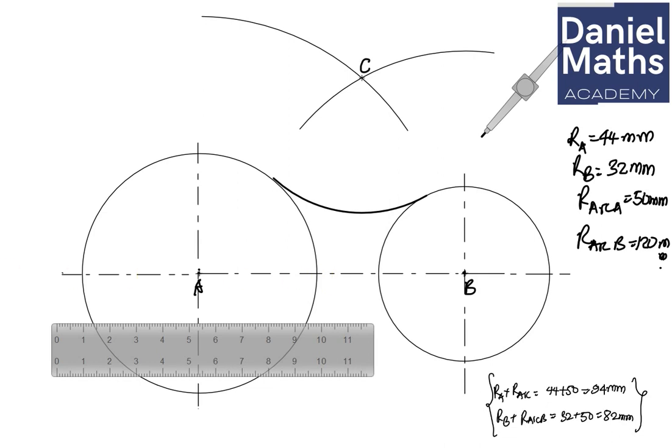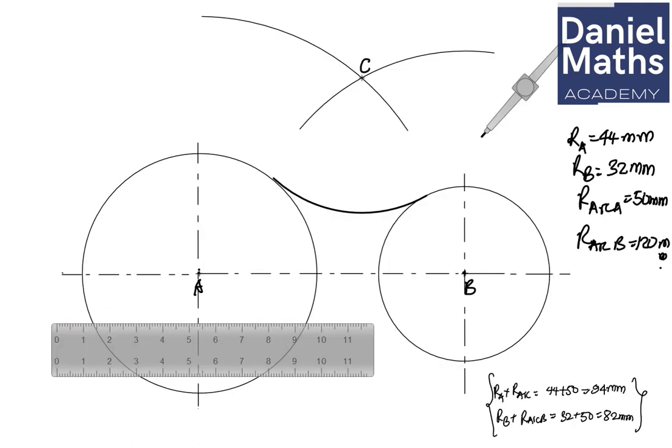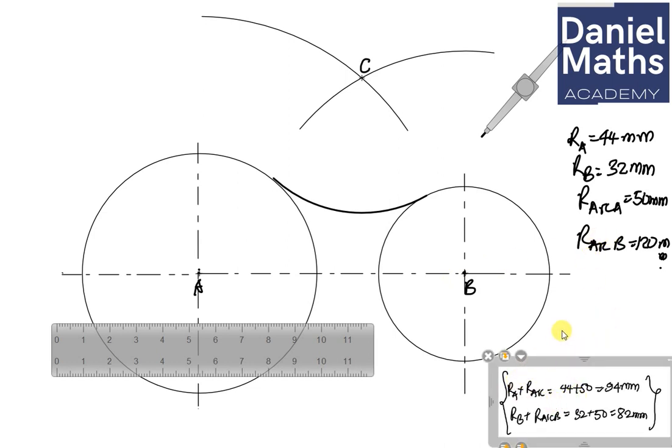To proceed with the new curve, I'm going to do the same thing, but now I'm using radius. This is externally now. Let me quickly make this clear so you can understand. Remember, we talked about the first one we added. But in this second case, when we're doing a tangent, we're using an arc to do a tangent for an internal, so the circle is inside of the arc. In the first case, the circle is outside of the arc. Now we have to join this to this point with the circle being inside the arc. So this gives internal. In internal we subtract.